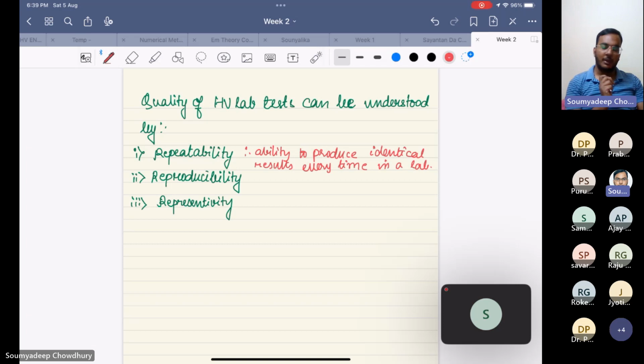All these things you have to tell the manufacturer or the utility person when they give you the insulator and when you give them back the certificate. You have to tell them how many times you have performed the test and what the breakdown voltages are, and then conclude that yes, my result is repeatable. So you can understand, you can trust my result. So everything is made public. Okay.